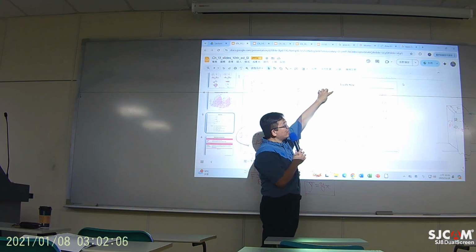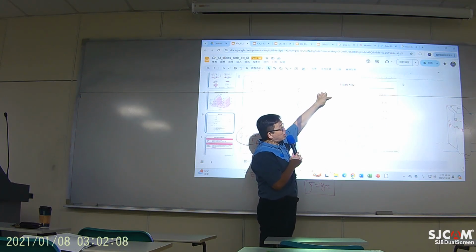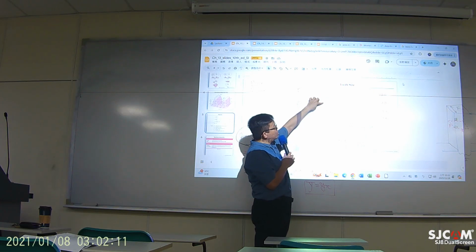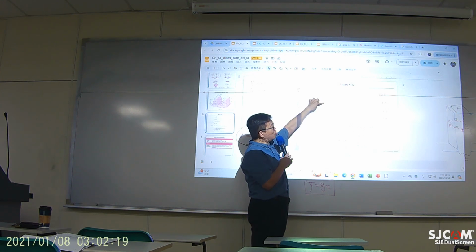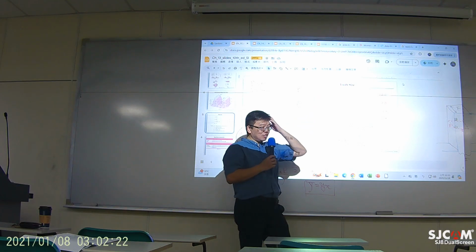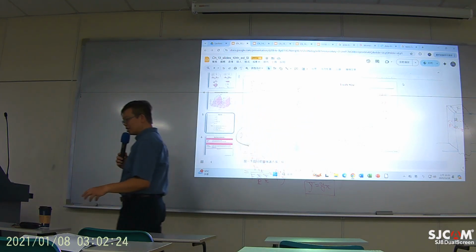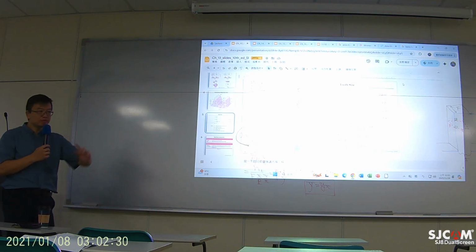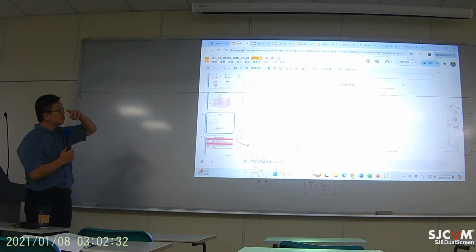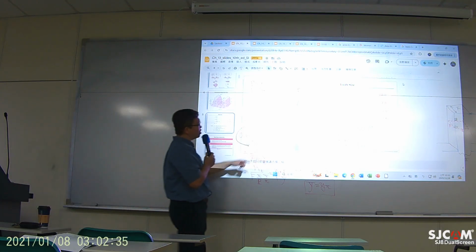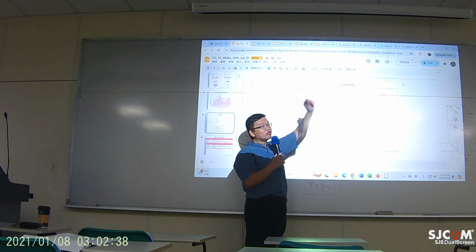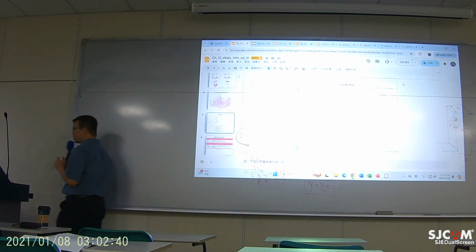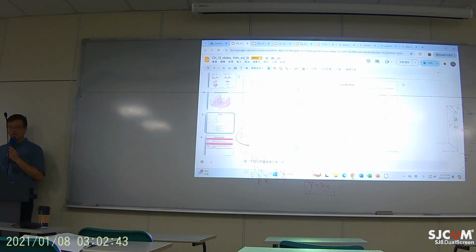It's the number of teeth over the pitch diameter, or inverse of your module. The module, not modulus, module. So usually when you purchase a gear, you know the value of module M. So if you invert it, the inverse of M, that's actually big P. So you usually know the capitalized P when you get the gear.